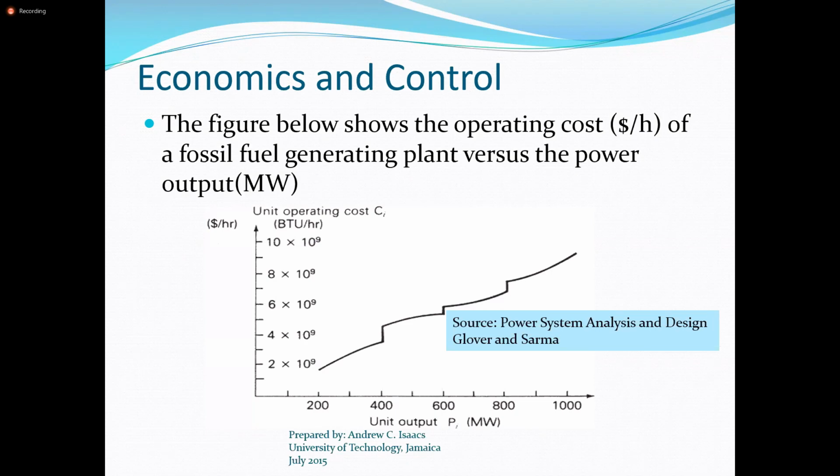Of course, we have already discussed the fact that I give you the method, so you don't have to worry about that. But let's now come to the whole business of discussion and coming to a conclusion. When I asked you to hold, for example, or to keep the active power fixed and to vary the reactive power, what will happen is that there will be changes in both the load angle and the voltage levels.